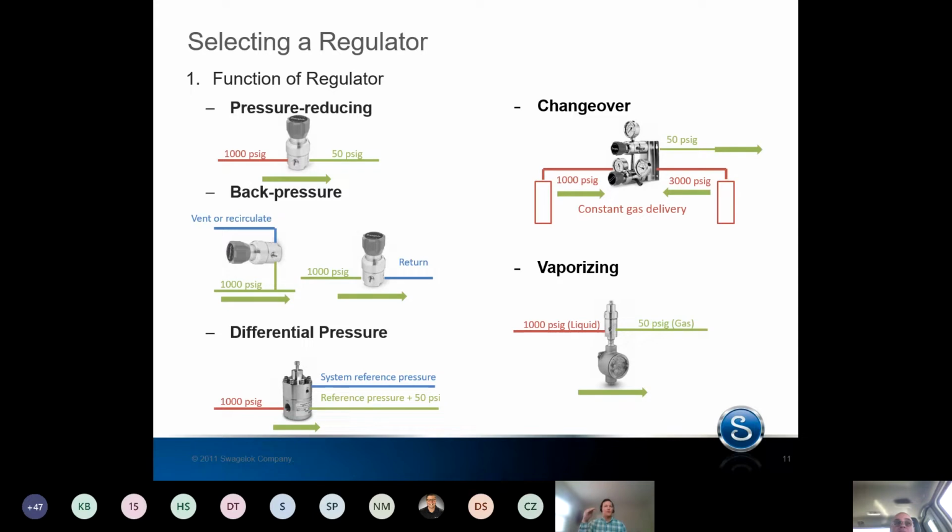The back pressure regulator is a very sensitive and repeatable way to open and close and shave off some of that excess pressure if you do have fluctuations. Or you can use it in line, and that really maintains an upstream pressure. We see this a lot on the backside of liquid analyzers in an analytical space.